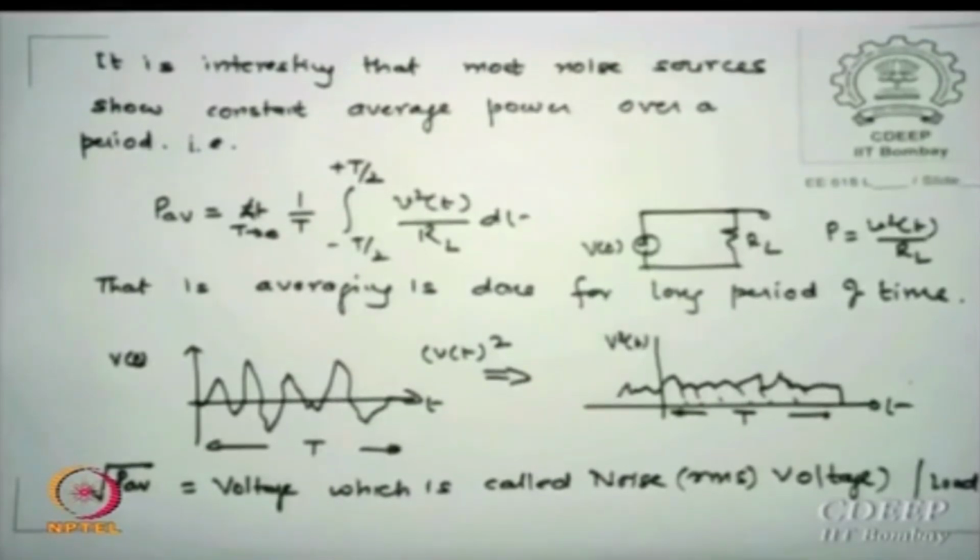In all normal analysis RL is chosen as 1 ohm. So voltage square is defined as watts, it looks to be, but we say V square. It should have been in watts, since power is in watts, but since R is always chosen as 1 ohm per se, the average power of a noise is essentially expressed in V square, that is voltage square.